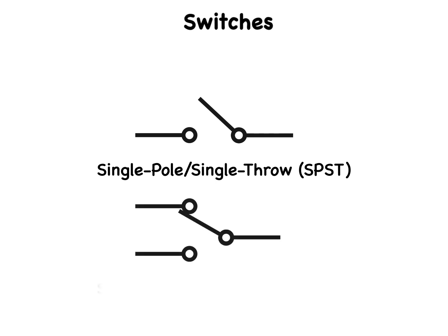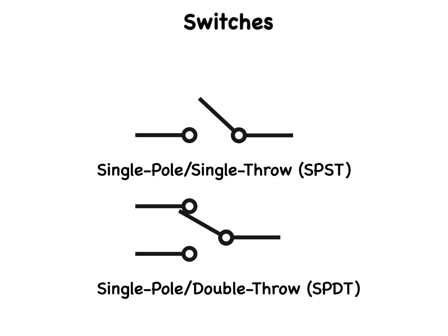A different type of switch, designated as a single-pole double-throw switch. Symbolically, the pole coincides with the point of contact at the base of the line. A throw is the contact point to which the line can point. The single-pole double-throw switch contains one pole contact and two throw positions. The input to the pole can be switched to either the upper or lower circuit point.